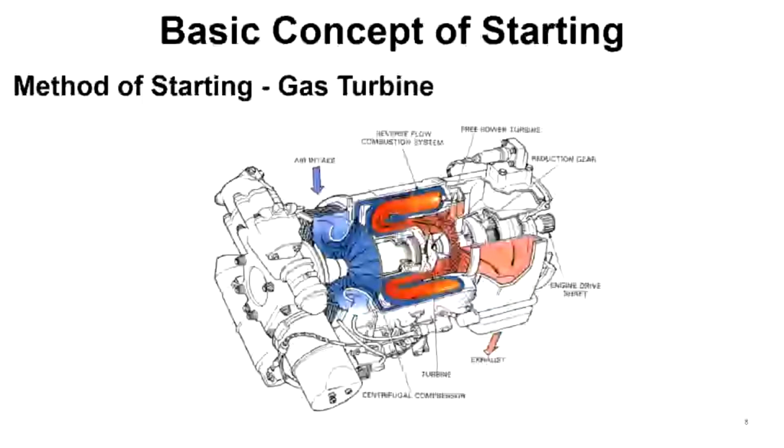Next, the method of gas turbine. It is used for some jet engines and is completely self-contained. It has its own fuel and ignition system, a starting system usually electric or hydraulic, and a self-contained oil system. This type of starter is economical to operate and provides a high power output for comparatively low weight.